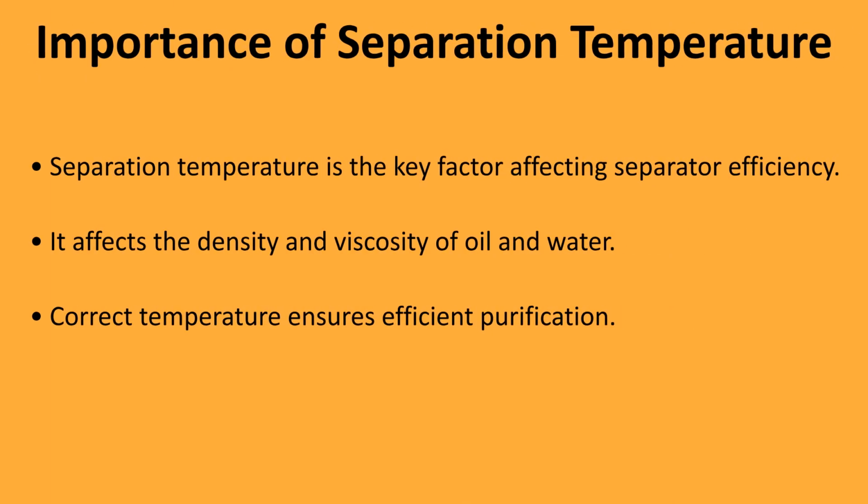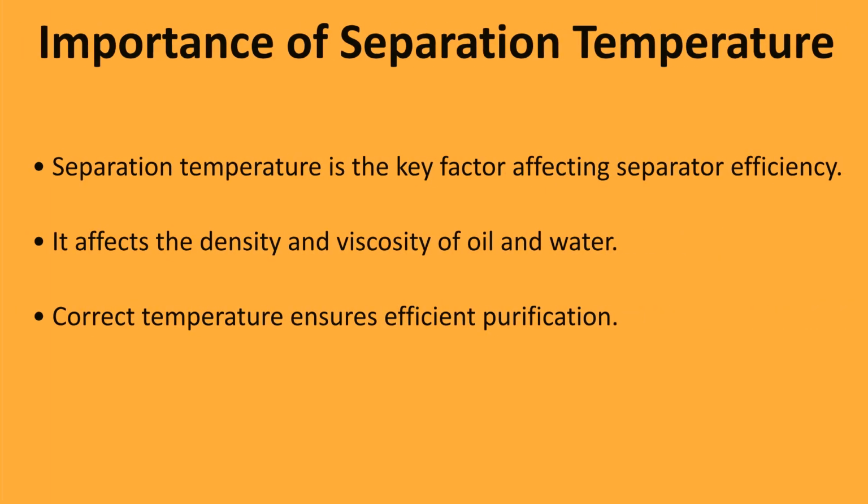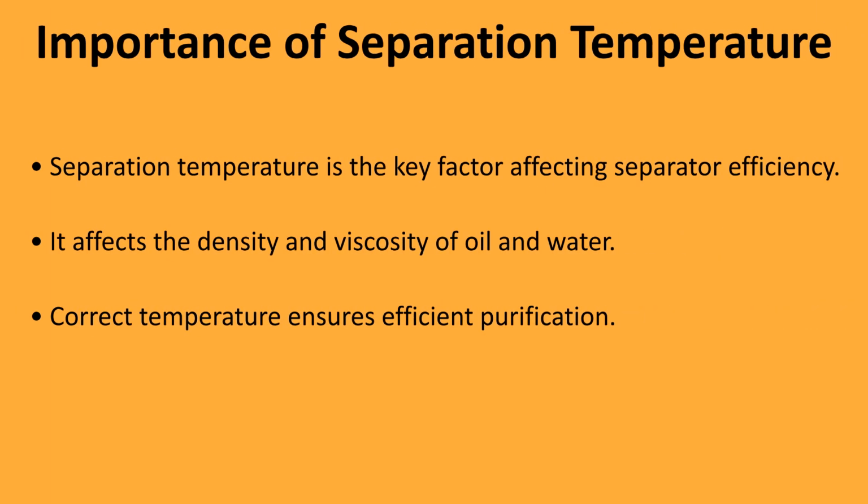The separation temperature is a critical factor for separator efficiency. It impacts both the density and viscosity of the oil and water, ensuring effective purification. Maintaining the correct temperature is essential for optimizing your system's performance. Always prioritize keeping the separation temperature within the specified range to avoid drops in efficiency.